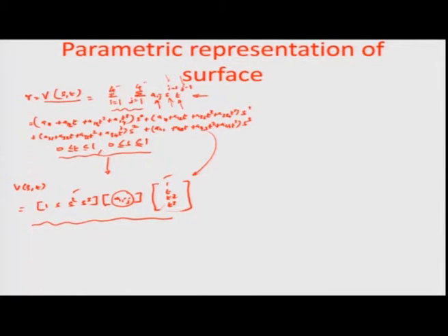Just as a planar curve would hinge to 2 points, the beginning and the end points, a surface would hinge to 4 points, like a rectangular or square surface corresponding to S0 T0, S0 T1, S1 T1, and then S1 T0. So, you will have 4 different end conditions this way, 4 slopes, along both the directions, and there are cross slopes.